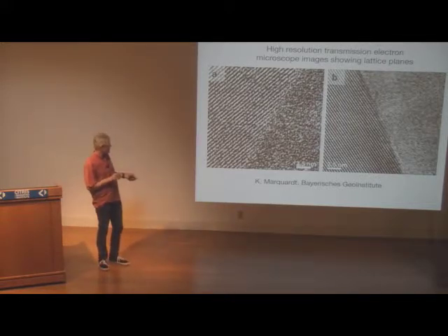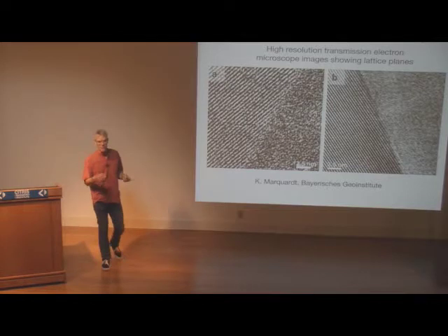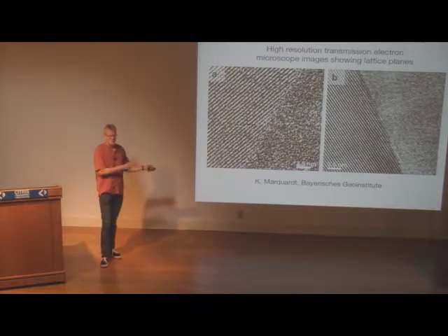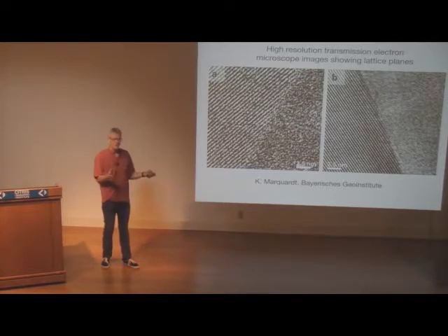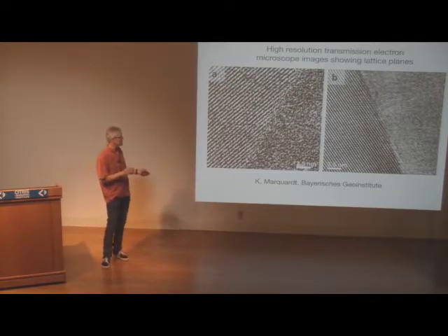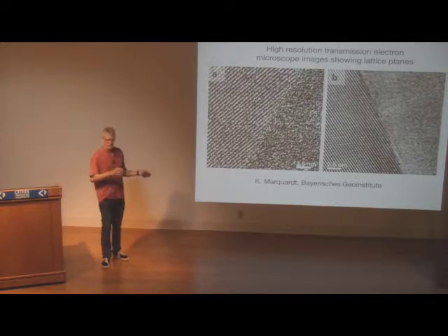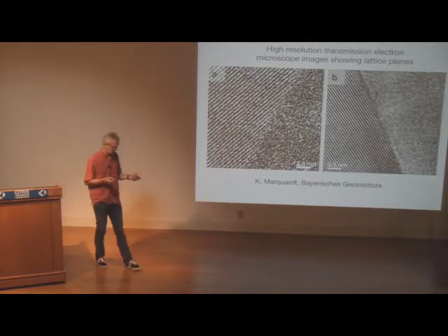So, understanding of grain boundaries: you can see again that certainly there's a region here where you have neither the symmetries nor the properties of the grain interior of this grain or this grain. It's more disordered. And more disordered means, for example, diffusivities will be higher along the grain boundary. There are models that invoke grain boundary sliding. I'll touch on those. So all of these models, in the end, fall back on what we know about the properties of these grain boundaries.